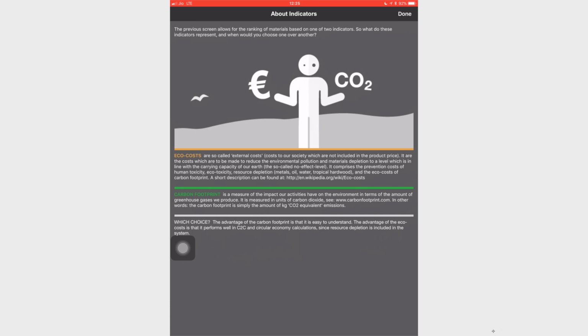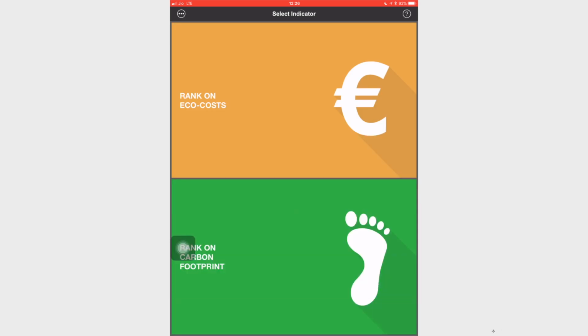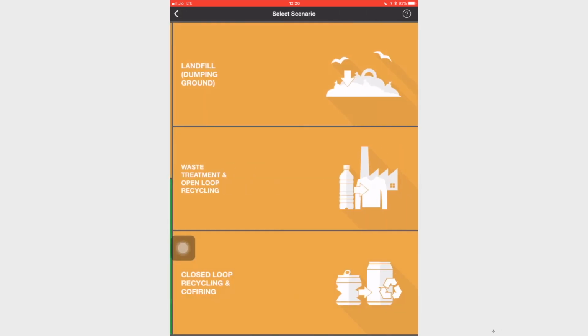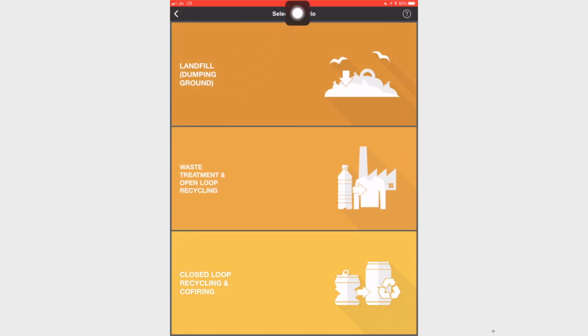Then my next product to be added is polypropylene. So, I will try to find out where polypropylene is. You can see here it is written polypropylene 30% GF. If you are confused, this is not the one that we are looking for. What it implies is polypropylene filled with 30% glass, so that is a composite. What I am looking for is only polypropylene. So, here is my polypropylene, the thermoplast which I am looking for. I will click on polypropylene and add it to my project.